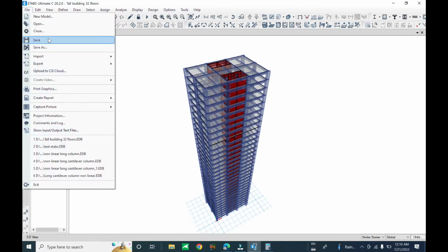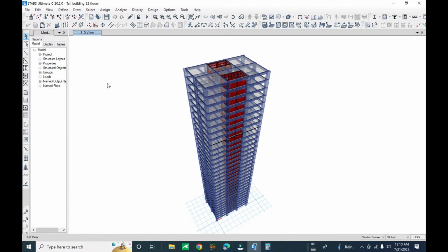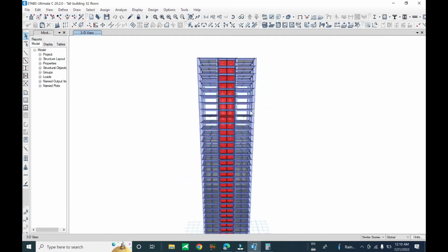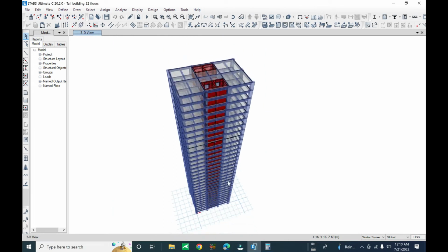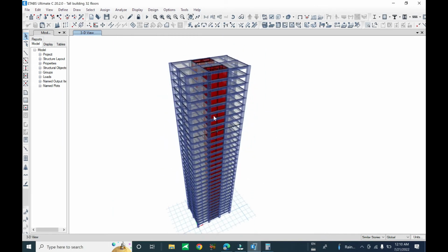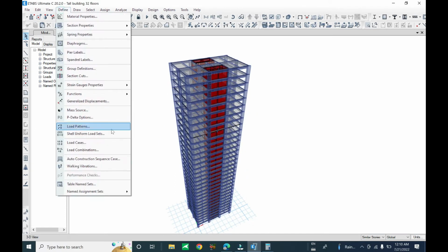In the first case, you have to run first order analysis and design, to check deflection and lateral twist, to make sure your structure can stand the load. After that, you can come back to run the second order analysis to verify. It is a step-by-step concept of how you can apply and check the global model, square and non-square. But if I don't want to care about this square and non-square, you can automatically use the non-linear P-delta analysis to get the maximum moment in the column.